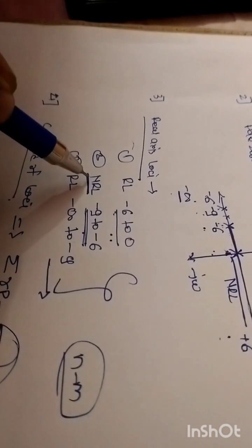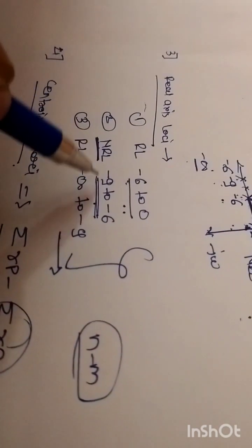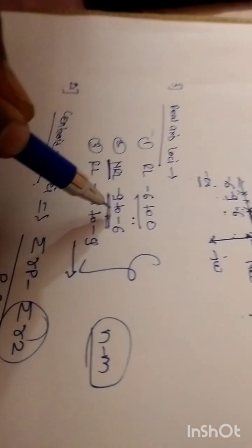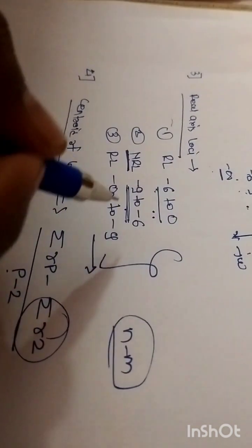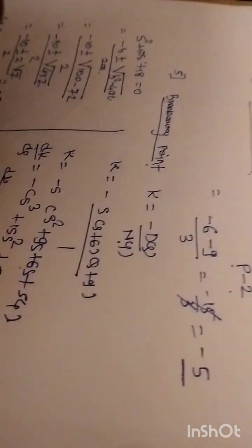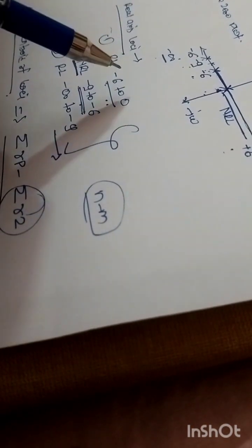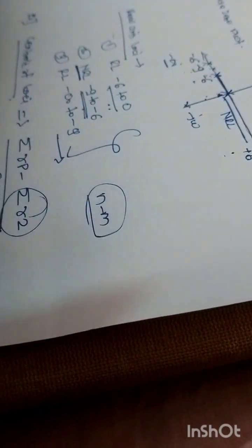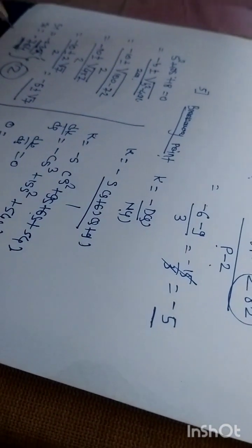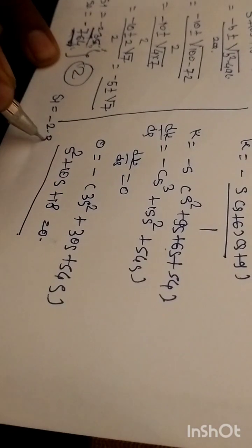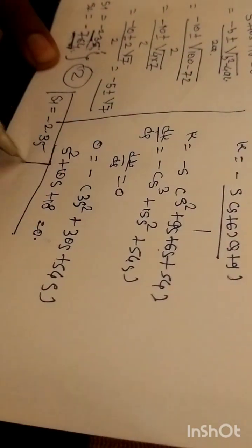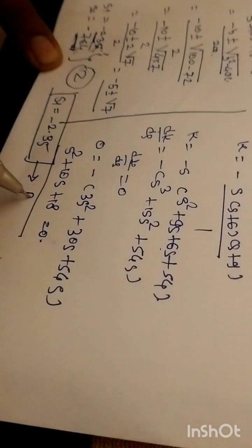NRL stands for no root locus in between minus 9 to minus 6. So definitely this second root, minus 7.64, lies in between minus 9 to minus 6, right? So, are you getting my point? Out of these two roots, s1 and s2, s1 is the valid root, that is minus 2.35. This is nothing but the breakaway point.